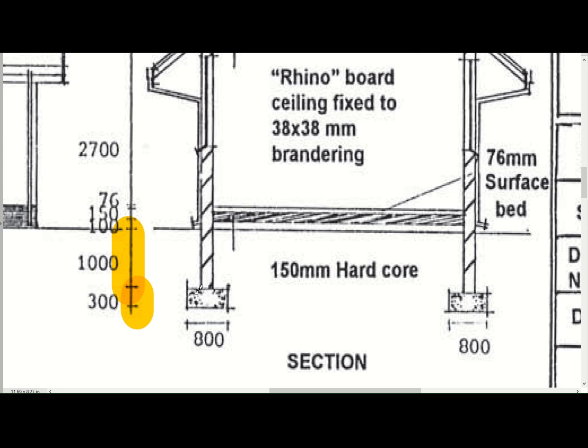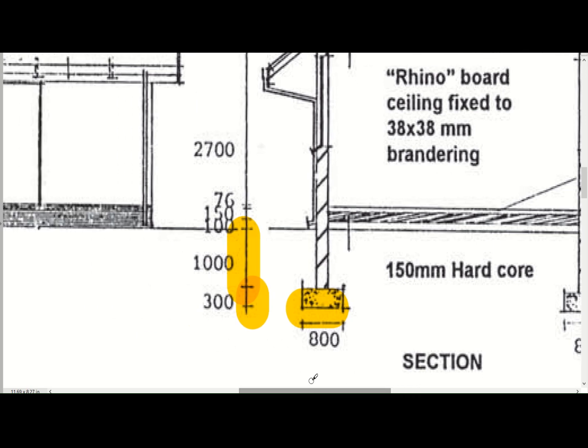Whenever you do your measurement in your bills of quantities, your excavations will be in cubes and not in meters like what we're measuring now. Then you will times it with your total length, that's 36 meters that you measured, times 800 mils times your height. So it's always length times your breadth times your height. That's usually the way to stagger it. It just makes life easy whenever someone else takes up your measurement. Okay, so that's more or less how the measurement works.